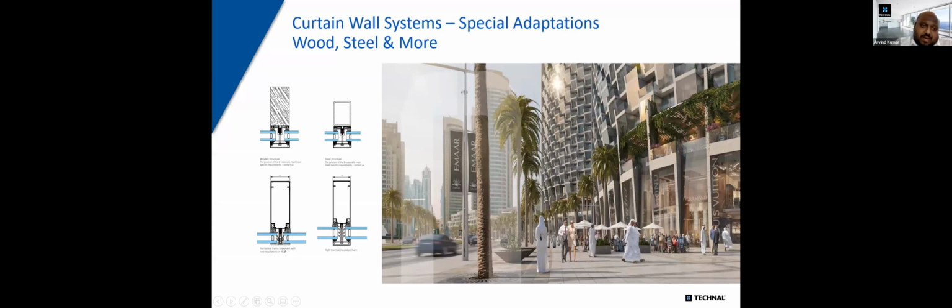So essentially, you have glass, which is held firmly by our aluminum add-on, and then the steel behaves like a structural component. We have new types of capping now. We have flat capping, which is very interesting for architects if they don't want to see that bulky extension. So this is also possible.